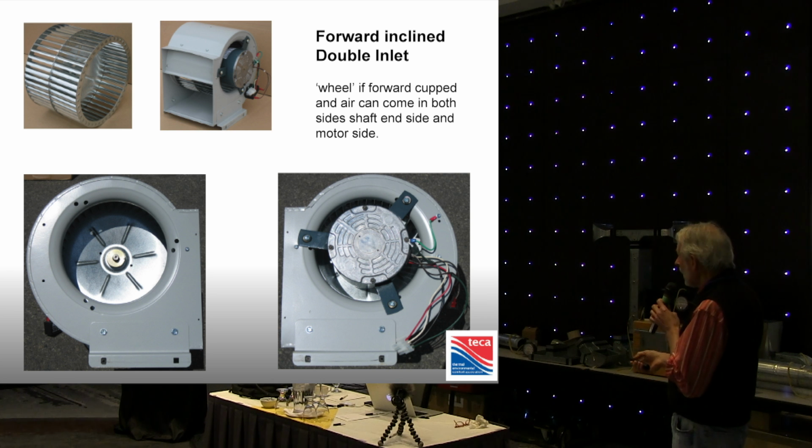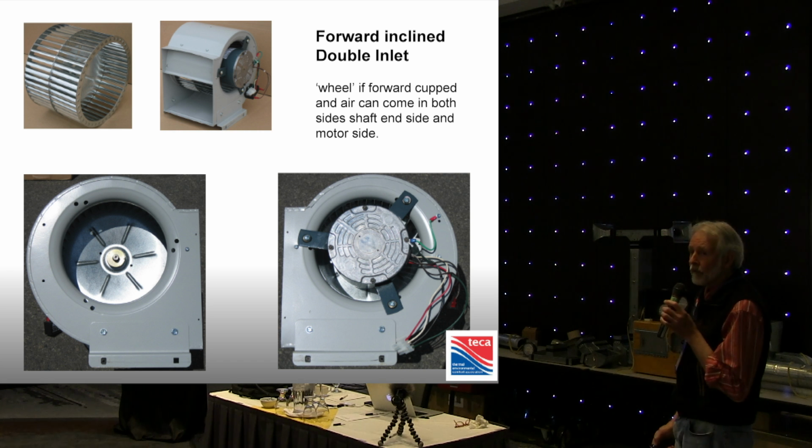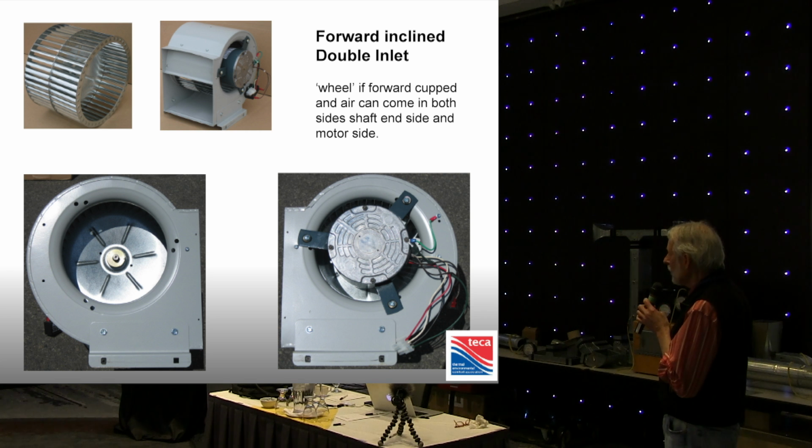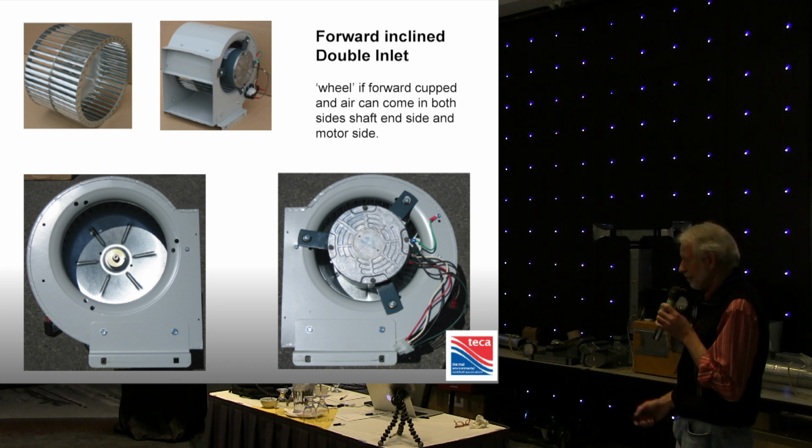And as you can see right now, the air enters this side of the fan unrestricted, but this side is blocked by half of its area with the motor, which is lousy design from the point of view of airflow, but it's extremely good because it's inexpensive and because the motor gets really good cooling.